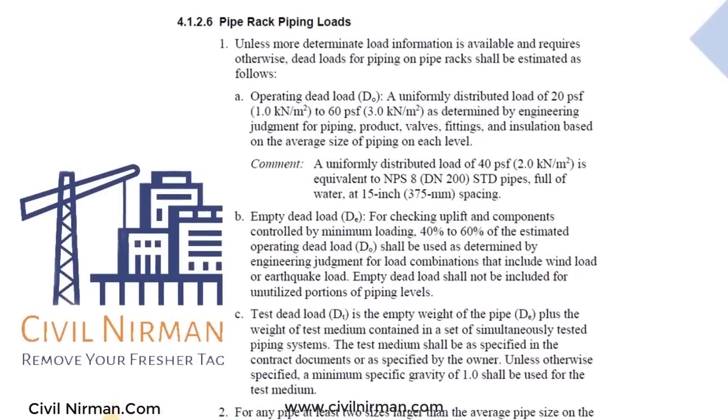Now let's talk about piping loads. The piping discipline generally provides the piping load input for big bore lines. So what is this big bore line? Pipe diameter equal to or more than 8 inch is considered as big bore lines, while line size below 8 inch is considered as small bore lines. Apart from that, piping provides input for some stress critical lines, irrespective of the line size. For the rest of the small bore pipelines, assumptions must be made for the load calculation.